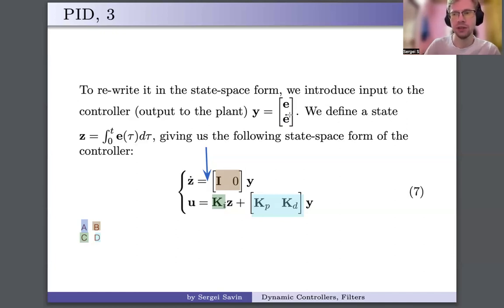You want the plant to produce fewer oscillations and less overshoot, etc. All of this is part of what you want. You want to understand exactly what you want, then you achieve it. And it can be done by simply, as we call it, turning the knobs. Like you make Ki smaller, you can make it bigger.